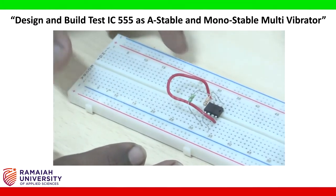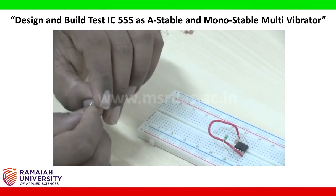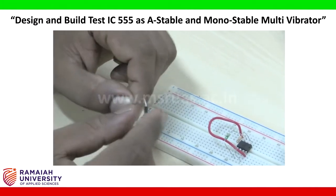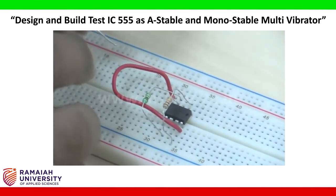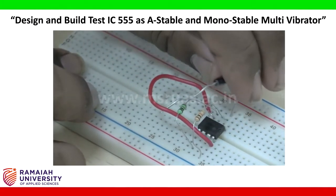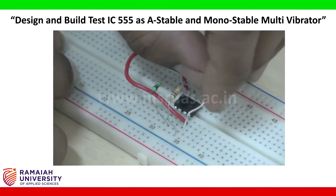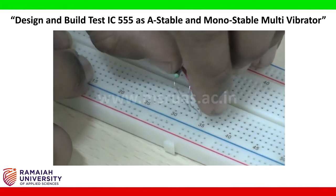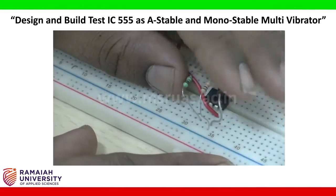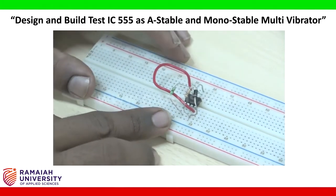Next, in the same way, I am connecting the diode. The negative of the diode will be connected to pin number 4 and the positive of the diode will be connected to pin number 2. So this is negative and this is positive. So here I am going to connect like this, with this pin. Now it will be connected in parallel to this 10 kilo ohm resistor.